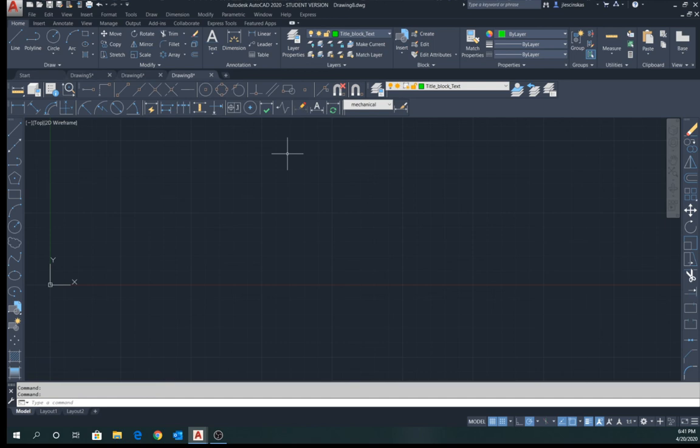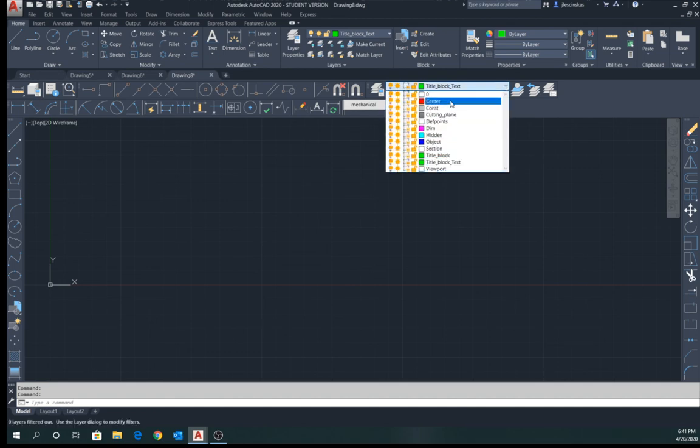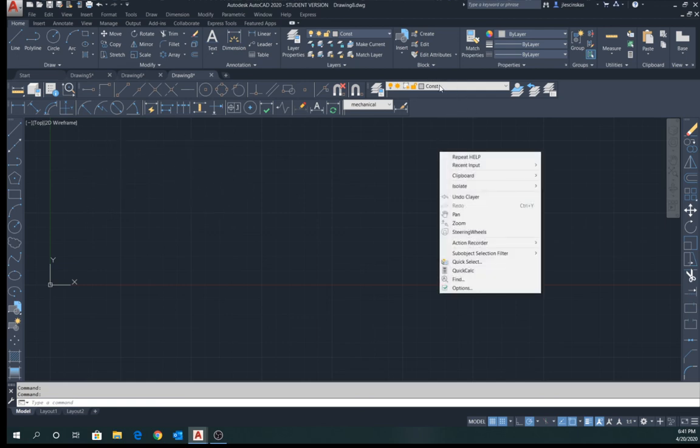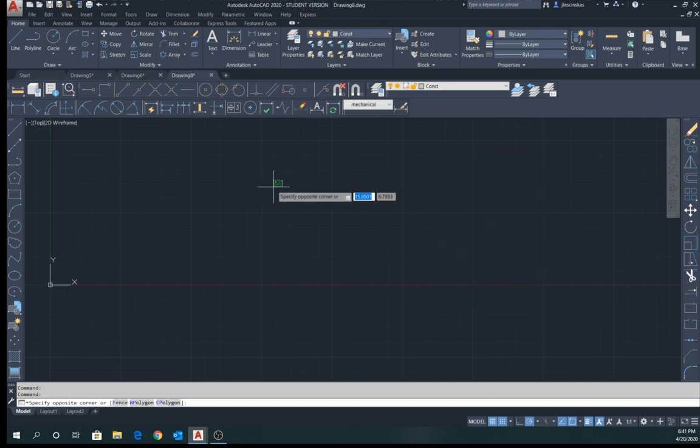Now, in creating this Geneva cam, one thing you're going to see is it actually can get created fairly quickly. And you may be a bit surprised at how quick it does get created. So what we're going to do is start in our construction layer, and we're going to start by creating some lines. So we're going to start with a construction line, and we're going to go to location 5, 4.5.